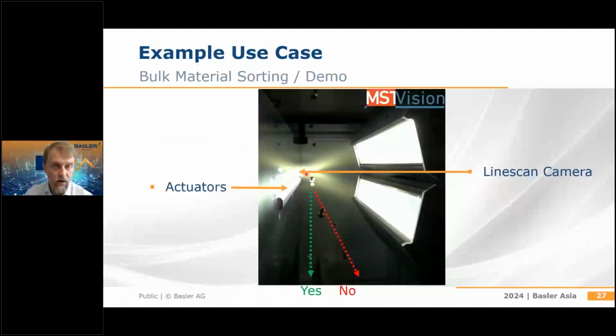Now I go into another case. It's about laser welding. So these two materials need to get welded together. The area scan camera, while it's running at very low resolution, but at a very high frame rate, requires a very fast pre-processing task. So here on the right, you can see a real world image where we measure the melting bath, and then by the size of the melting bath and how it's looking like, it's decided if the laser being used is applying more or less power.